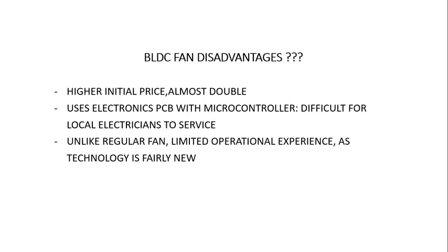Are there any disadvantages for BLDC fan? It is told like this, but let us examine. Higher initial price, almost double, but we have seen that in the first year itself you save the money which you have paid as higher price. So it is not a big issue.